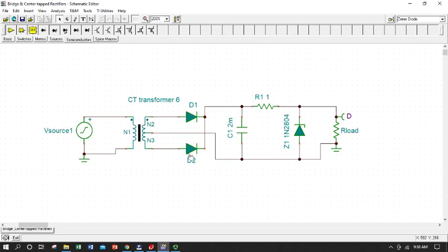We have our rectifying diodes that give us pulse DC that take that negative going signal and basically flip it up. So we have our double the frequency full wave pulsed DC. We got a smoothing capacitor that continues to give us a voltage signal even when that pulse drops when we roll down off of our peaks.